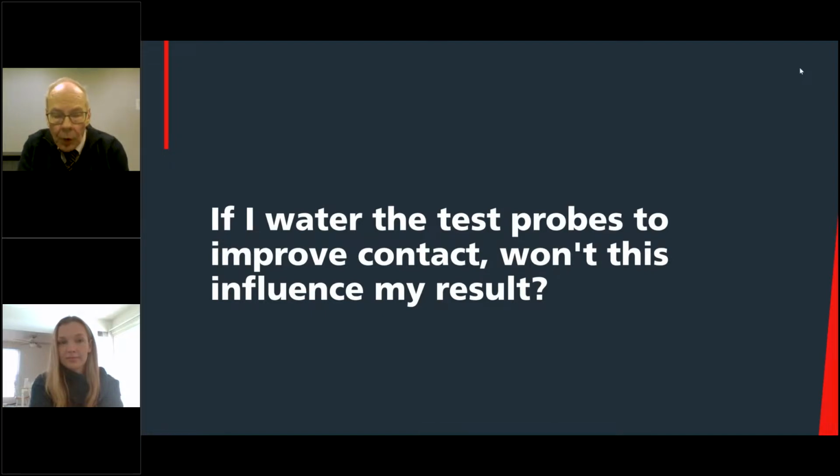If you pour water on your test ground, then yeah, you're certainly going to influence your result. So, not to be funny or anything, but if you want to fool the inspector, before he gets there, you can water your test ground. It will certainly lower the resistance.